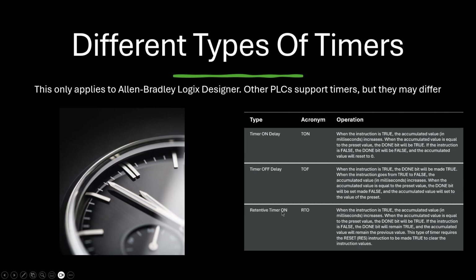So the retentive timer is the only one that you must use a reset tag or a reset instruction to clear the data of the timer.